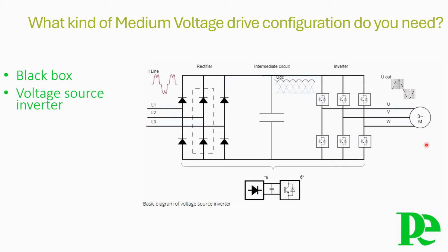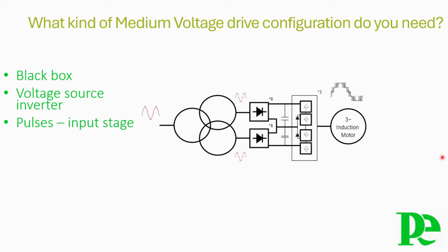In fact, when referring to a 6-pulse drive, we relate to a standard rectifier bridge containing 6 diodes, resulting in a 6-pulse DC voltage. The three-level drive depicted in this figure is made up of two 6-pulse rectifiers supplied by a 3-winding transformer. We call this a 12-pulse in-feed. The secondary windings of this 3-winding transformer have a phase shift of 30 electrical degrees, thereby cancelling the 5th and the 7th harmonics on the primary side. This 12-pulse in-feed results in lower line harmonic distortions. Indeed, the AC line input current of the 12-pulse drive looks already a lot better than the 6-pulse one.